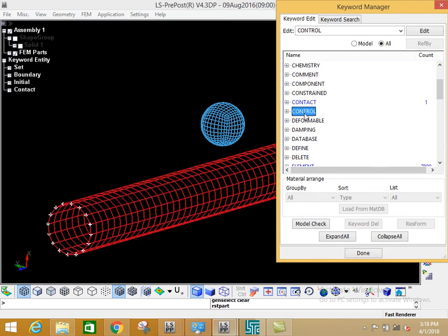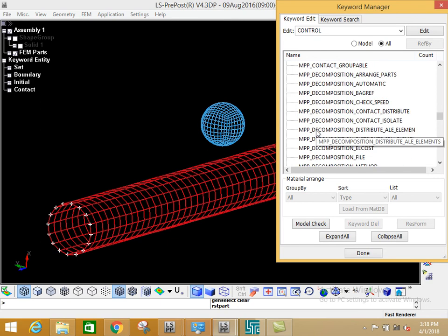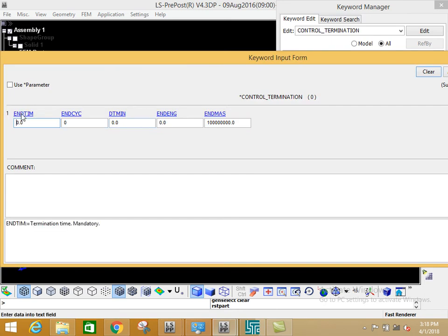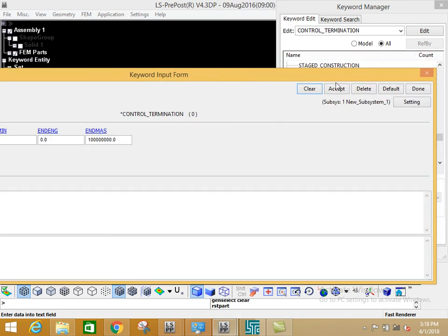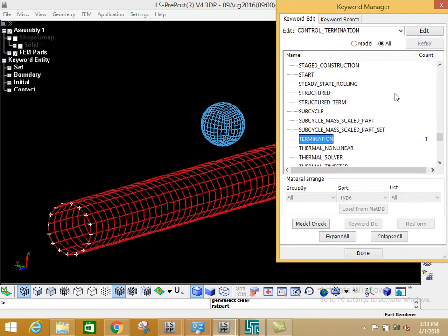We go to control, scroll down until you see termination. Okay, end time. Let's say our end time of this simulation is 50. Then click on accept, and I think that's all done.